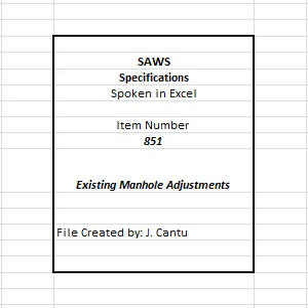D. ASTM D790, Flexural Properties of Unreinforced and Reinforced Plastics and Electrical Insulating Materials. E. ASTM D1238, Standard Test Method for Melt Flow Rates of Thermoplastics by Extrusion Plastometer. F. ASTM D1505, Standard Test Method for Density of Plastics by the Density Gradient Technique.